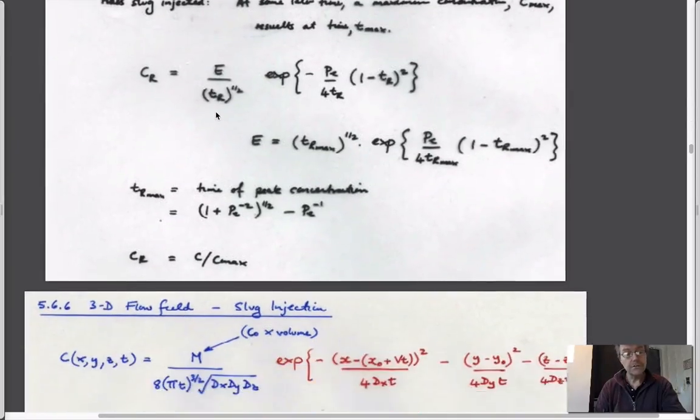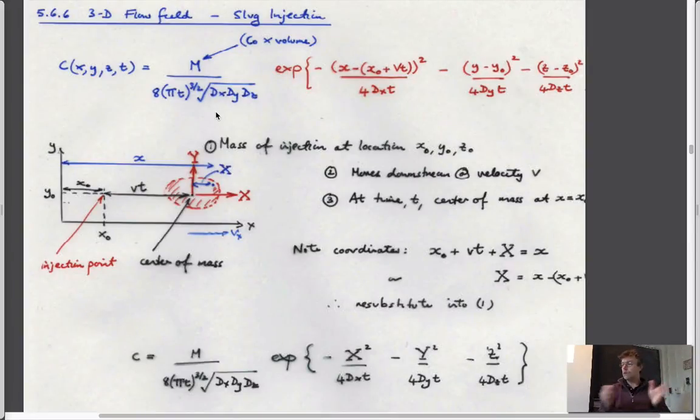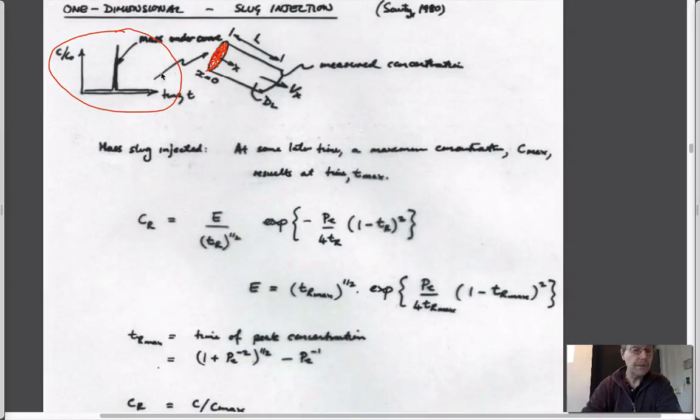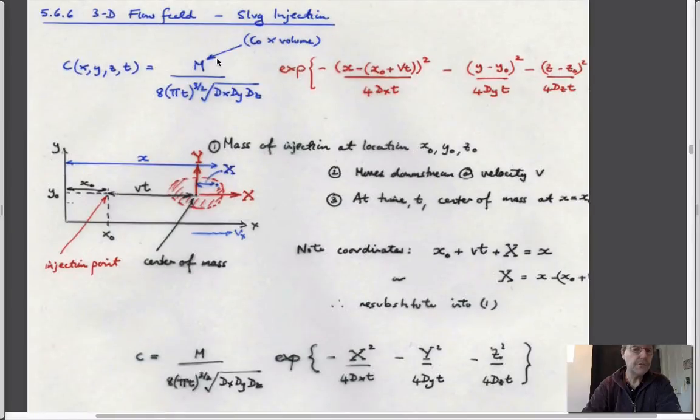And so the two solutions that I'd say are important are the one we just talked about, where we get these residence time distributions in terms of relative concentration, pore volumes and Peclet numbers, which we spent a bit of time talking about. That's for a step increase in concentration, and really represents that you continue to dissolve stuff from upstream and it replenishes itself as it gets washed downstream. The opposite of that is this delta function, where you inject something either into a core plug like this or perhaps more reasonably into an aquifer.